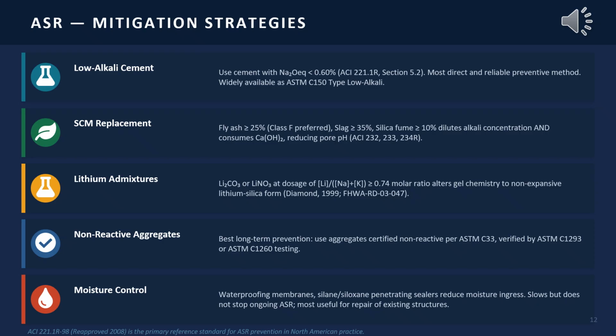Finally, moisture control through waterproofing and sealers can slow ASR progression in existing structures, but it cannot stop it once it has begun. It buys time for repair planning.